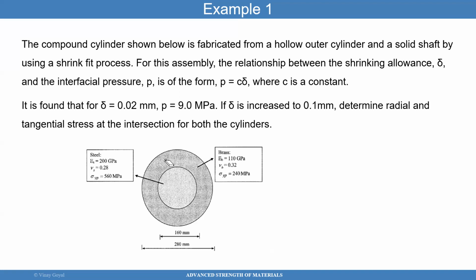So the thing I want to put in is bigger, and so I had to apply cold temperature, bring it in, and then let it come to room temperature, and that's causing a pressure. Can you envision what I'm saying or no? But that amount of difference is 0.02 is what this problem statement is saying, and they figured out somehow that the pressure is 9 megapascals, and I showed you in some ways how that can be measured.